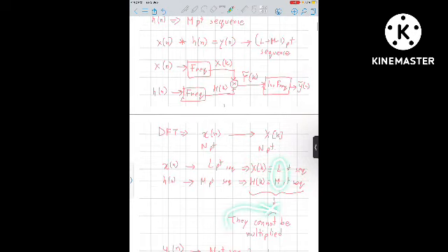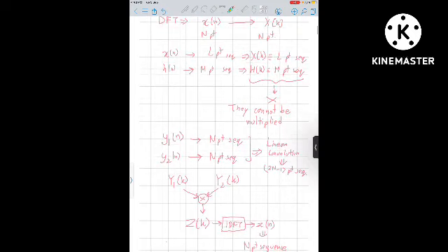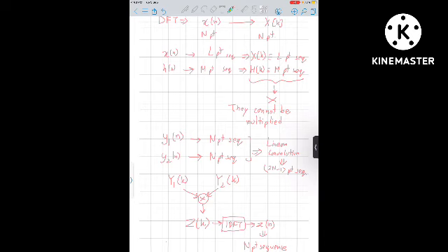So now we again visit back to the case of same length sequence. Let's suppose y1 is an n-point sequence and y2 is also an n-point sequence. If we are supposed to have linear convolution, we get a 2n minus 1 point sequence, because n plus n minus 1. Okay, so we have the corresponding transforms y1 of k and y2 of k, which are also n-point transforms. We multiply them and obtain some n-point sequence again, that's z of k.